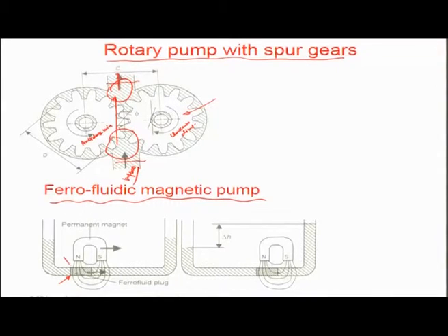This could be, for example, an oil immersing iron oxide particles, which doesn't mix with the overall water in the system, and it is activated as a plug. You can see this hatched area here, acting like a plug. The idea is that when an external actuation is done through a magnetic field, it magnetizes, and as this U-shaped horseshoe magnet is moved in a certain direction, it drags the plug along with it.